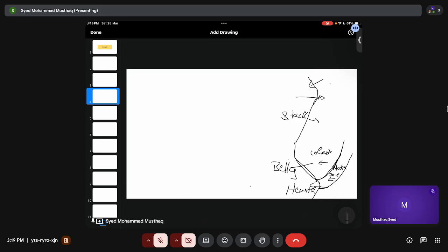The cohesive zone forms because of the temperature rise. When you are going from bottom to top, the adiabatic flame temperature reaches 1950 degrees centigrade at the bottom, and that's why the temperature goes down as you move from bottom to top, right? And because the temperature is very high, whatever iron has remained will become cohesive. That means it will become soft.